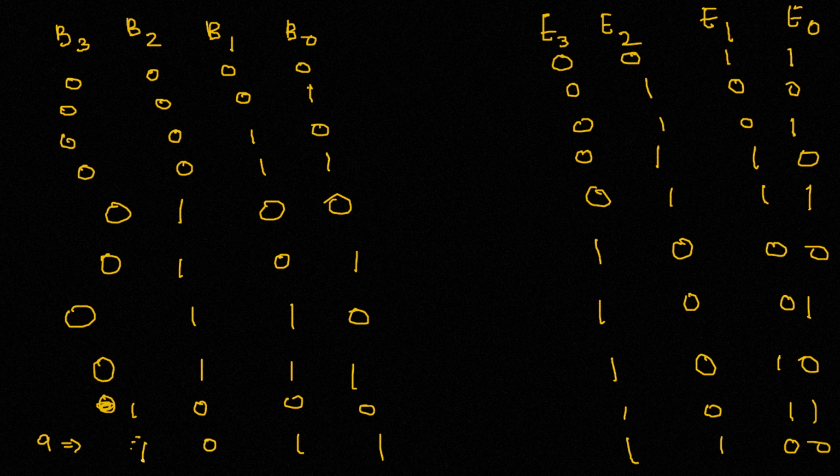Okay, so this is the binary equivalent of the decimal number 9, right? So we stop at this because we are talking about binary coded decimals alone. So decimal numbers range from 0 to 9. After this, the entire table would be just a don't care condition because it doesn't matter after this point, as we are not going to get any binary coded decimal for decimal numbers higher than 9. So everything below this is a don't care.